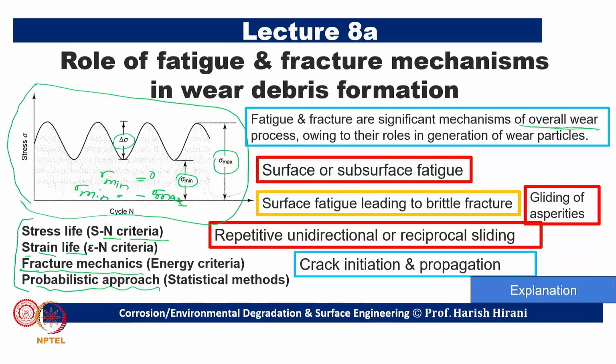Another point when I talk about fatigue is whether it is surface fatigue or subsurface fatigue. In my earlier lecture, I mentioned that 70 to 80% of the time fatigue starts from the surface because of some sort of discontinuity. However, there is also a possibility of subsurface cracks or subsurface fatigue. We will explain this to some extent in this lecture. I also mentioned that many times fatigue causes brittle fracture. Even in ductile material, because of repetitive cycles, the material behavior changes, brittleness increases, and that causes fracture. We will deliberate on that to some extent also.